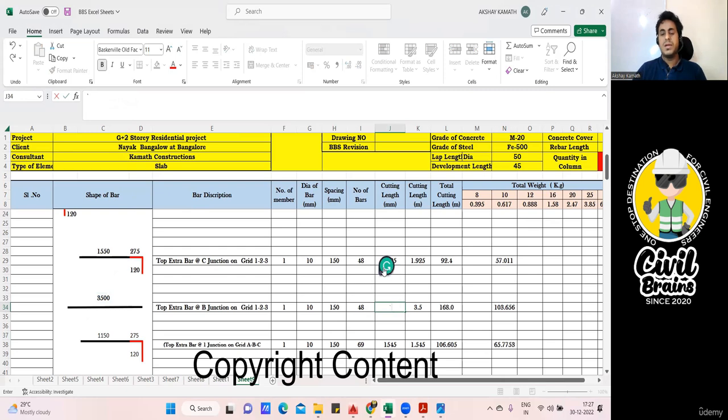So if you divide it by 1000, it will be 3.5 meter. And the total cutting length will be 3.5 into 48 into 1, which finishes at 168 meter. Then the weight of the 10 diameter bar is 168 multiplied by 0.617, and you'll get 103.656 kg. Finish. So in this way, we have done the top extra bar.